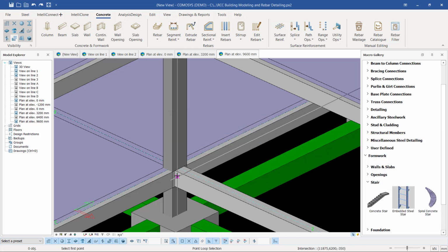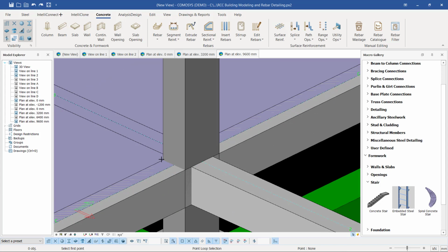I'm going to define 2 points. The first point I'll click, the second point I'll just mouse over and press enter on my keyboard. So I'll click on this particular point and mouse over on this particular point. I will now press enter on my keyboard. This will provide a field where I can feed in a dx to define the direction of my staircase. So 2340, then I'll press enter right there.